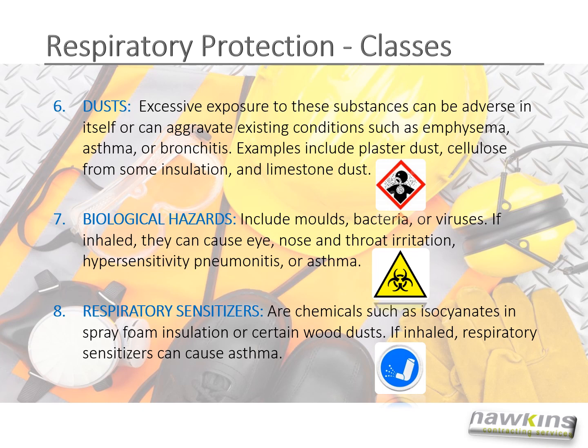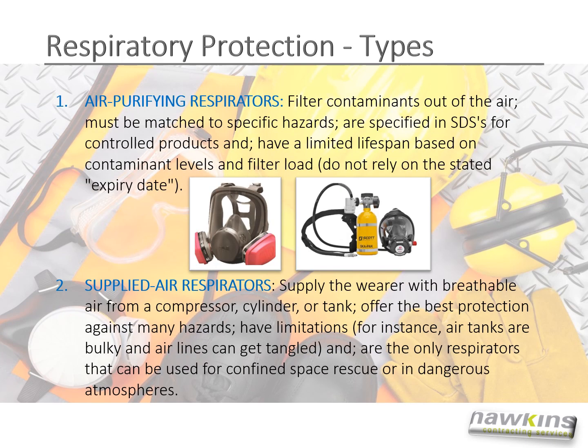Respiratory sensitizers are chemicals such as isocyanates in spray foam insulation or certain wood dusts. If inhaled, respiratory sensitizers can cause asthma. There are 2 types of respiratory protection. The first is air purifying respirators. They filter contaminants out of the air.